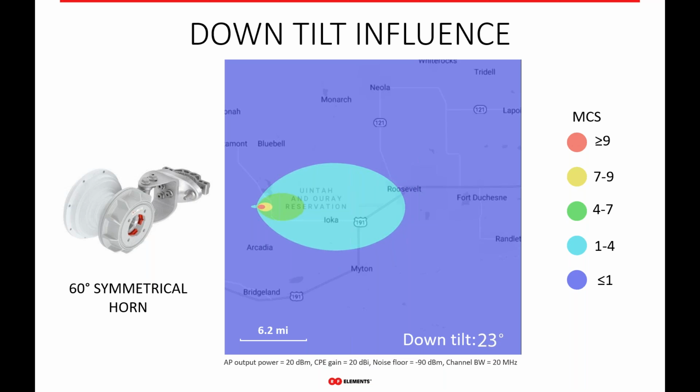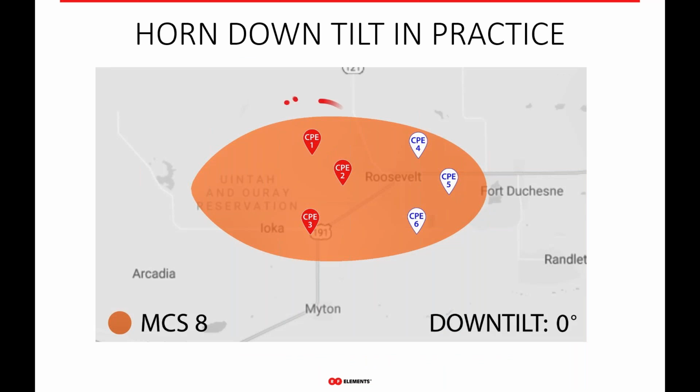By using the down tilt, you can dramatically improve the noise conditions for your network by simply setting up the down tilt based on the furthest customer throughput requirements, right? This way, the antenna only delivers and receives signals from as far as necessary. Again, with patch array sectors, it's almost binary: you put a little bit, 1 degree too much, and you lose your customers at distance. With our horn antennas, the gradual change of coverage area allows you to fine-tune your coverage area, minimize noise and maximize gain to your actual customers out in the field.